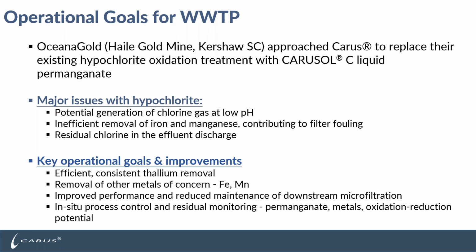Some of the issues that were encountered with the previous hypochlorite treatment included the potential generation of chlorine gas at low pH, inefficient removal of iron and manganese, which was contributing to significant fouling of their downstream microfiltration process, and also residual chlorine being present in the effluent discharge. So this excess chlorine often required the use of sodium bisulfite to dechlorinate the water prior to discharge to their outfall.